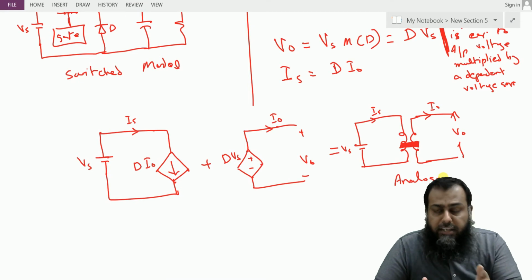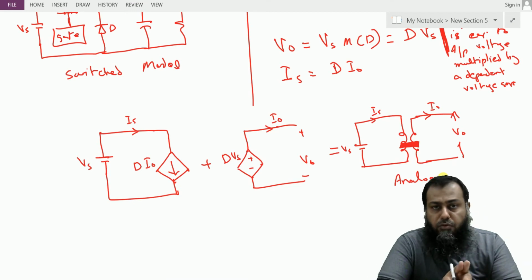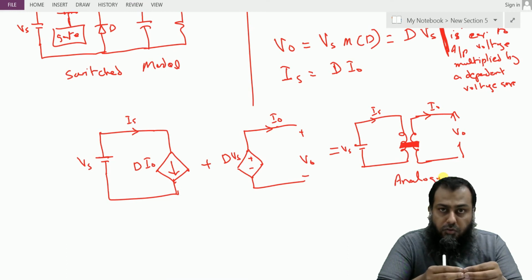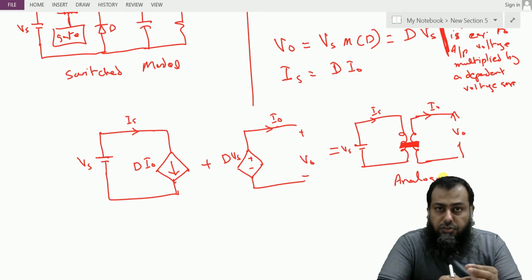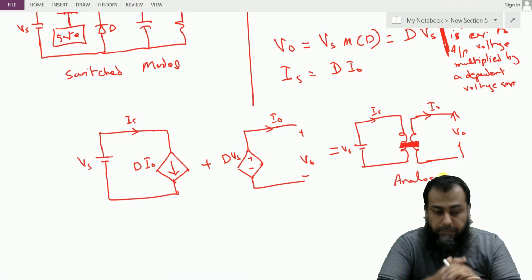The voltage and the current are averaged, and therefore the output contains the transient behavior. However, because it is averaged, it does not place a burden on the computation requirement, and it happens more efficiently and swiftly compared to a cycle to cycle conversion or a switched modeling concept.